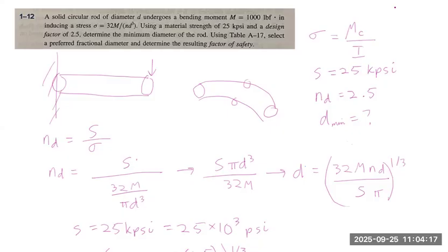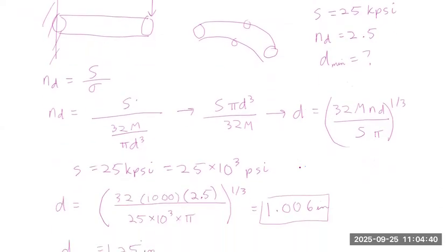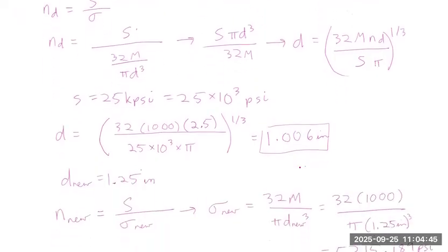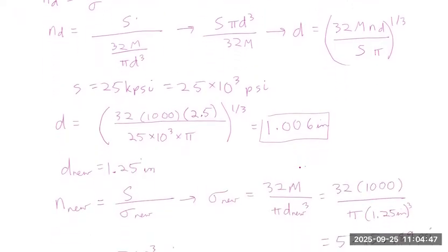Engineers select a preferred size from this standard list to ensure that the final part can be manufactured efficiently and cost effectively while still meeting the necessary strength and safety requirements for the application. As you see over here, it's basically due to manufacturing and the standards that manufacturing needs. It would be incredibly hard to manufacture a diameter of 1.006 inches with precision, and it's unnecessary.